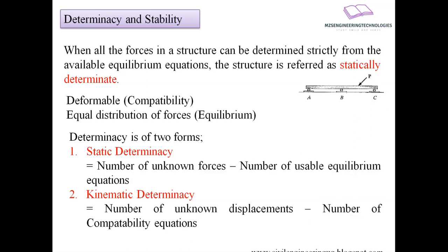Let's discuss with reference to a figure here. We are seeing a continuous beam having continuous supports A, B, C, D. Roller supports are there, over which an applied load P acts, inclined with reference to the horizontal plane. If we prepare the free body diagram, we find that there are three forces generated due to the end conditions: Fa, Fb, and Fc, which are the reactive forces going in the upward direction.